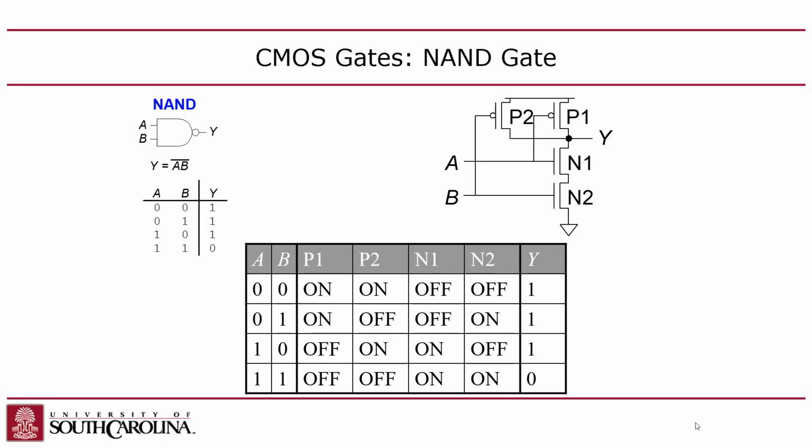Now, there is an important limitation of this, though. What kind of sucks about CMOS is that if you look at the truth table, at all the rows where there's a 1, all the rows that give you a pull-up condition, I have to have at least one input as a 0 in order to achieve that.